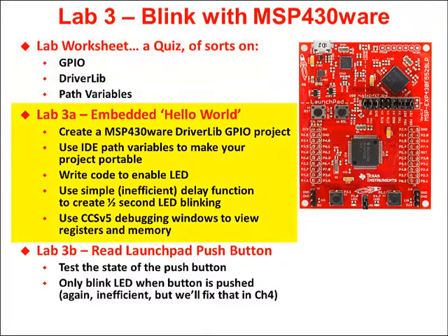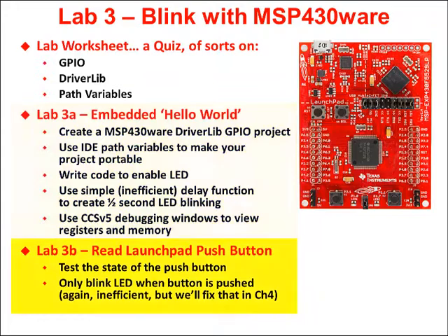The two actual exercises we're going to do is we're going to do an embedded hello world. Hello world of embedded systems is blinking an LED. So that's what we're going to be doing here. We're going to do it using driver library. Then the second part is going to be reading one of the push buttons from the LaunchPad. So we'll get a chance to see that. When we see the button pushed, we'll light the LED. When we see the button not pushed, we'll not light the LED.